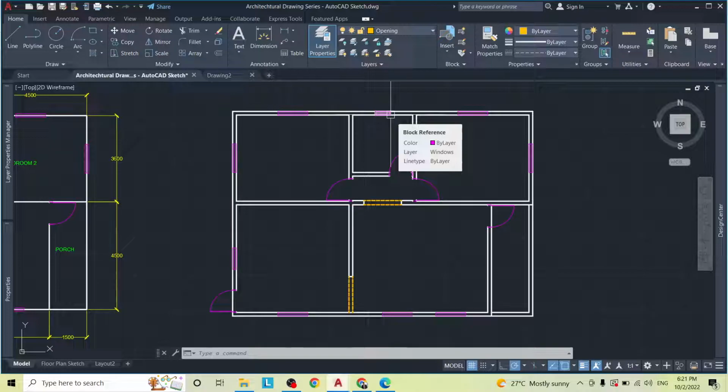This cut is usually made around 4 feet from the floor of the house. So imagine if you stand up in your house and then you measure 4 feet up, that's a foot higher than where your window begins, and then you just make a horizontal cut all the way through all of your walls, and then you throw away the top half of that house, and then you go above and look down on top of it. The floor plan is what you would see.